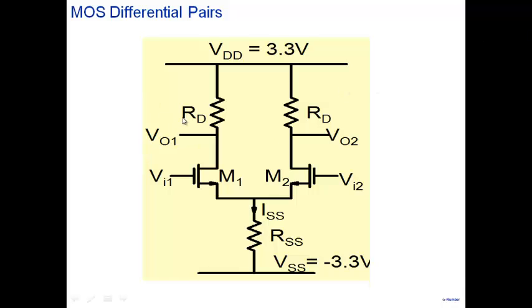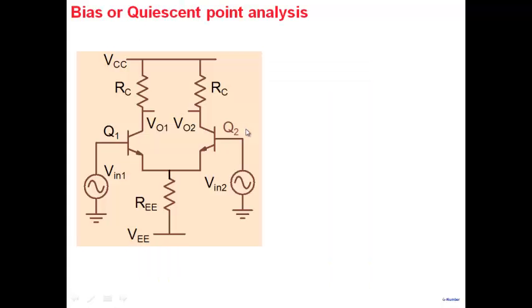We see here that as a load, we can use RD. As a load, we can replace RD by a transistor. And this is nothing but biasing, and we have seen at several places current source biasing. So we know directly that this can be replaced by a transistor, and this replaced by a transistor. So in the context of amplifiers, in the context of biasing, yes, I can do it. But I don't want to make any absolute statement. There are places where you can't do it.